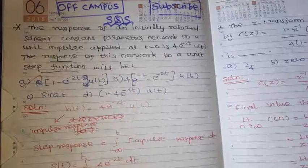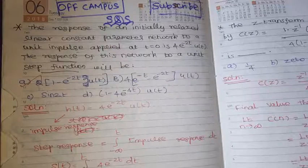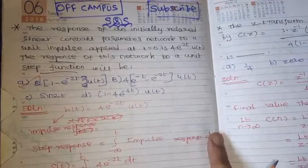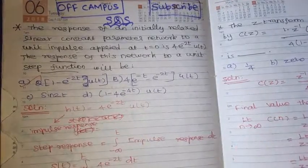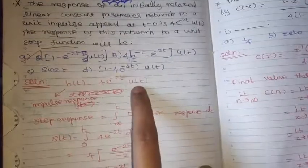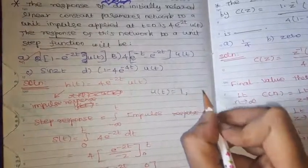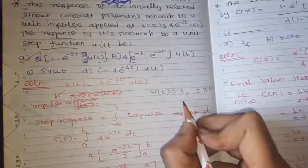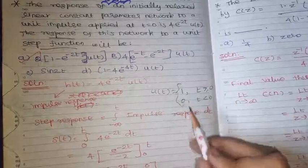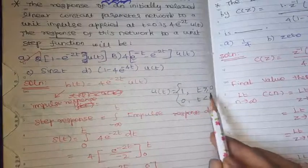To find the step response from the impulse response, just integrate the impulse response over the limit minus infinity to t with respect to time. Impulse response is given as 4 e power minus 2t into u of t. What is u of t? U of t is a unit step function: u of t equal to 1 for t greater than or equal to 0, and 0 otherwise, for t less than 0. So u of t will be 1 for 0 to infinity.